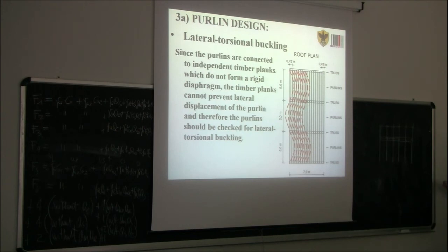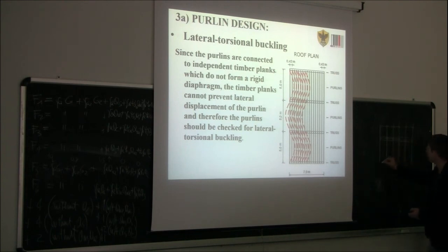And then, of course, you don't nail one plank which is, I don't remember the length, but the length of this will be 3.5 meters. Usually the plank is not 3.5, it's a little bit less, so there could also be discontinuity. So in the end, this one is not enough to prevent a global buckling like this.